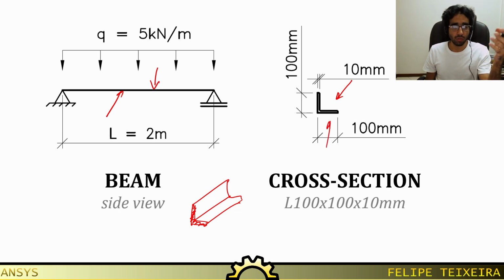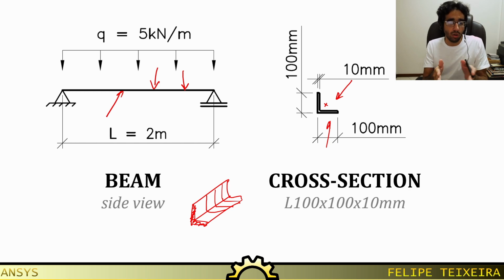What is the relationship between this line and this cross section? And this is how this works. This line passes through the centroid, the center of mass of the cross section. So this real three-dimensional structure is being imagined as a bunch of thin cross sections. So you can stack an infinite number of these sections to get our three-dimensional beam.